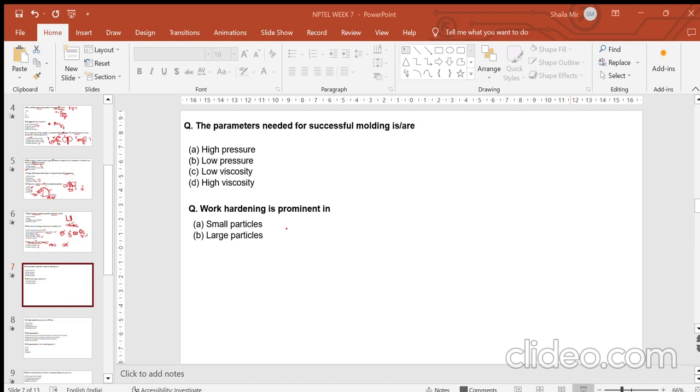And in this, only the main ingredients, we are not considering lubricant or binder. Why? It depends. When you are forming a powder and you want to calculate the theoretical density, then you should take all those into consideration, right? But if you are using a binder in 0.1% or 1%, there will not be a significant difference, based on what kind of proportion you are using. But if you are using two powders, 50% powder A and 50% powder B to form an alloy, then there is going to be a significant difference in density.